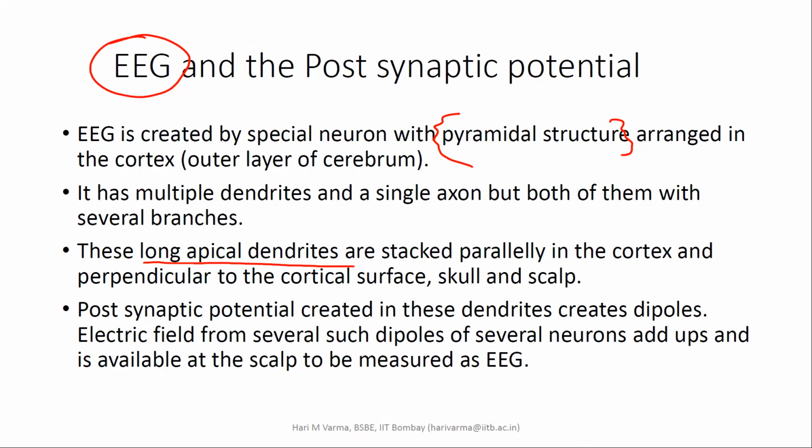If you look at this EEG, it is something that is picked up from the brain, from the scalp, right? So we put a lot of electrodes on the human scalp, and these electrodes are in a jelly-like medium which acts like an electrolyte, right? So if there is an electrical signal in the scalp, that will cause a redistribution of ions across this electrode, which can be measured, and which is manifested as the EEG signals that you might have seen in hospitals, right?